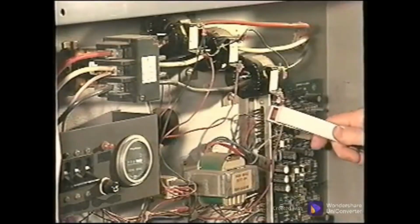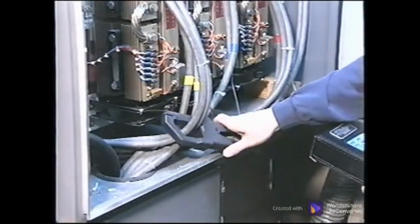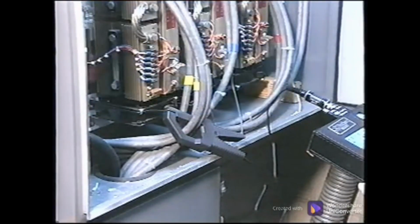For safety, we recommend that current measurements be made at the CT or current transformer rather than the actual phase line. Never exceed the safe voltage limits for the current clamp, which is usually rated at 600 volts. Follow all safety guidelines for collecting this data. Once baseline current data is collected, you can make other measurements which provide the same information and more without having to access an electrical cabinet. These are flux measurements and are discussed in the next section.